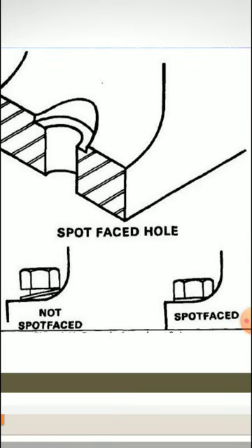Okay, so when it is spot faced, the bolt can properly fit, and when it is not, due to the roundness or due to the sloping nature of that material geometry, the bolt is not able to fit into that position.